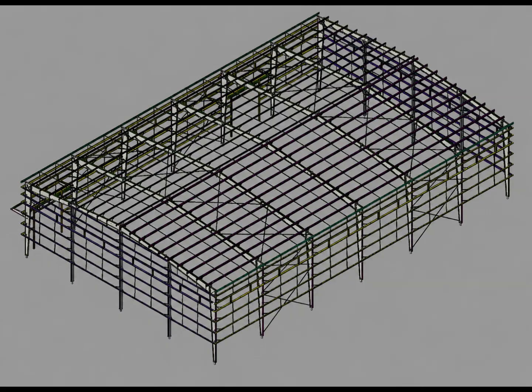From a drafting and detailing point of view, this 3D view can also be used as a coordination check. For example, we can inspect whether a bracing member is reaching the intended connection location. We can check whether secondary members are positioned at the correct levels. We can inspect whether the roof framing follows the intended slope. We can identify whether any members appear to interfere with other members. And we can use different views of the model to better understand complicated connections.